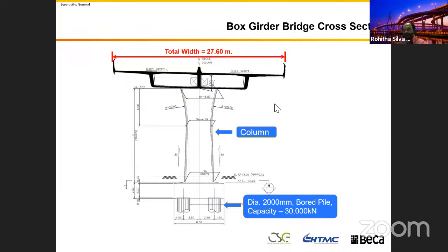These design solutions came to optimize the design as well as to get a better outcome, right? It's using the whole environment, especially the ground condition. Trust me, you can't do the same thing if you have shallow rock like 5 meters below, like sandstone we found in some places in Sydney.